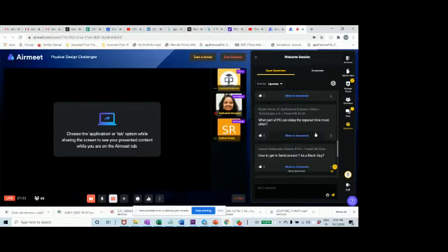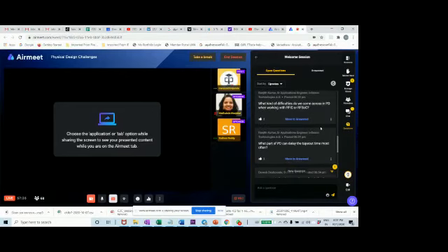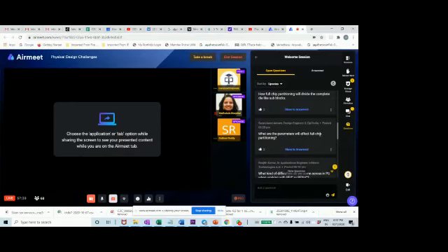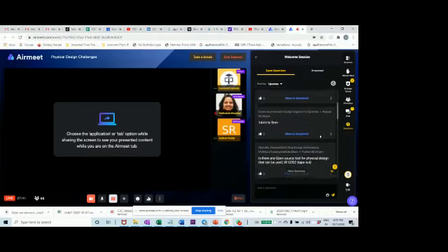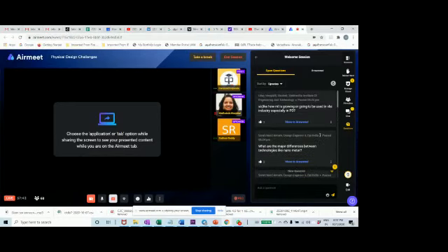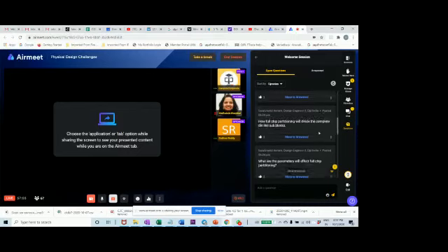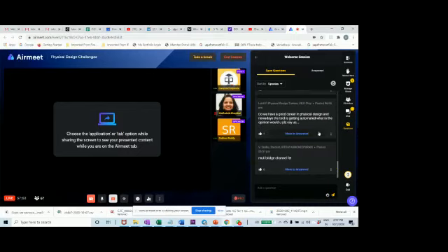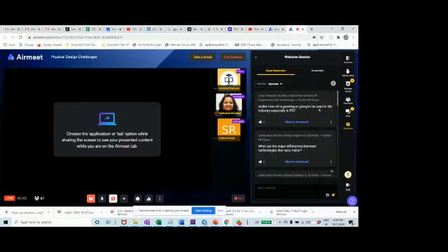a signal to enable or disable the bias. It's mainly for low power design. So if you want to bias your transistors so that your threshold voltages can be altered and hence your performance can be changed depending on the scenario. Let's say if you want to use it in a turbo mode, you want to have higher performance, then you can. But when you play with your bias, the leakage will vary. So you will have higher leakage when your performance goes up.